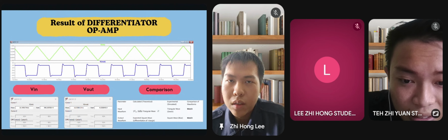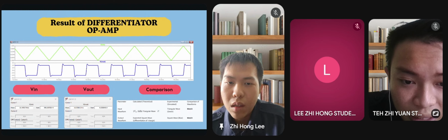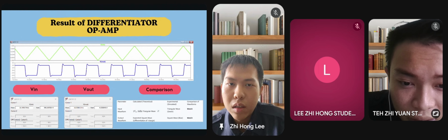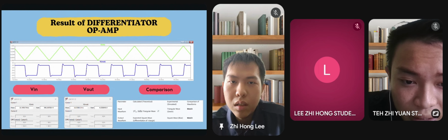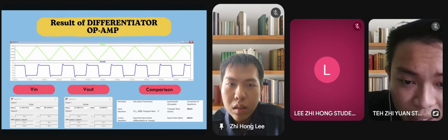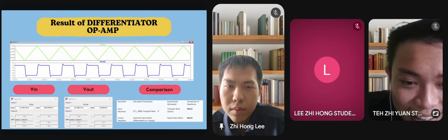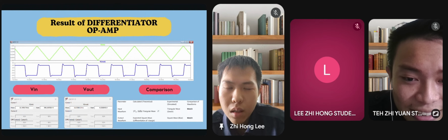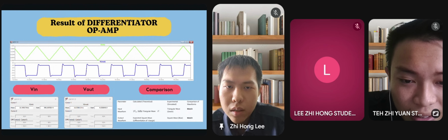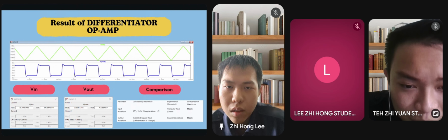critical for noise immunity. An ideal differentiator amplifies high frequency noise extensively. The capacitor limits this high frequency gain, acting as a low pass filter to ensure stability and reduce noise. A necessary trade-off to prevent the output from being overwhelmed by noise.